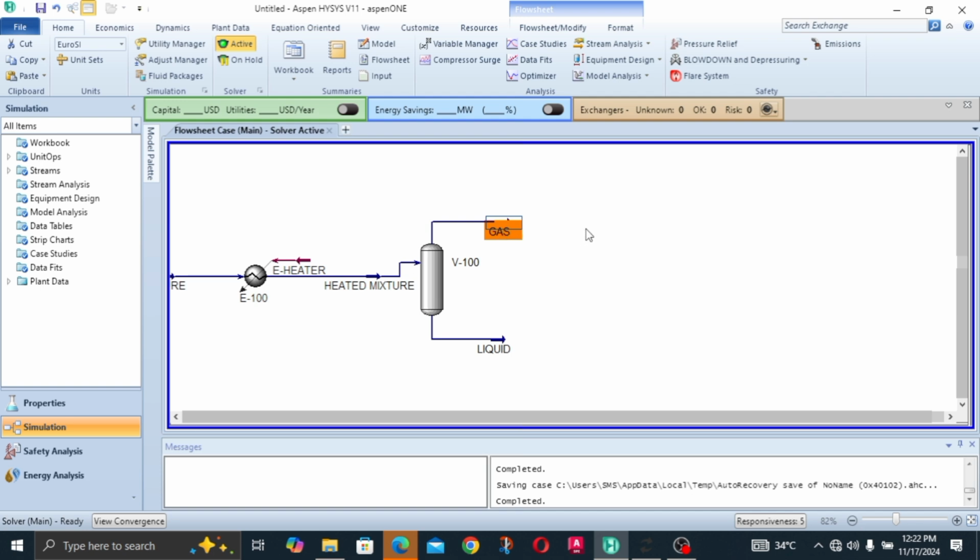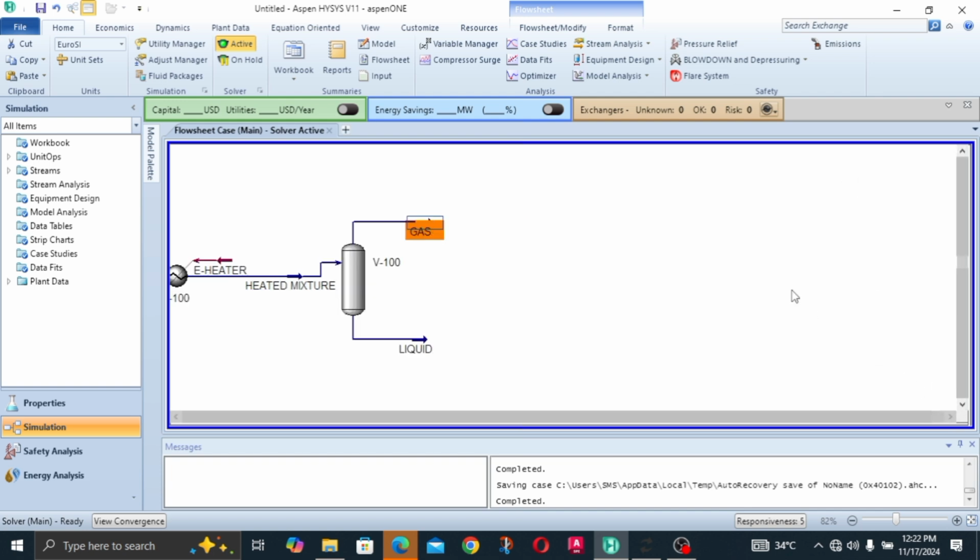So if we do a little bit of cooling and separation again, when we cool, the vapor fraction drops from 1 to 0 point something, and then we drop a separator, and with that at the bottom of the second separator, we would be having water at the bottom. So we could keep doing a series of this cooling and separating until we're able to actually separate them completely, 100%. But that takes time and is a little bit too stressful.